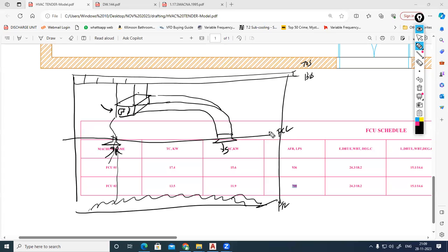Since the false ceiling is a closed compartment above, when the blower fan is taking the suction, the only opening from the space is the return diffuser. Through the return diffuser, the return air will be going inside. The machine fan will take it. It will be circulated through the cooling coil. The temperature will be decreased, sensible and latent heat will be removed. Then after that, through the duct, it will be distributed.